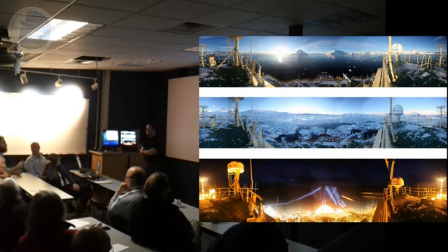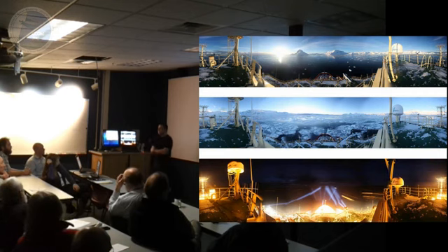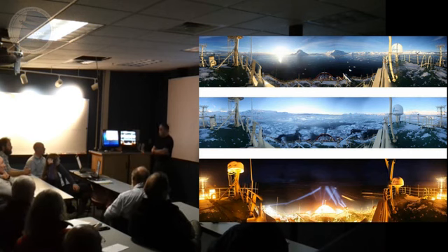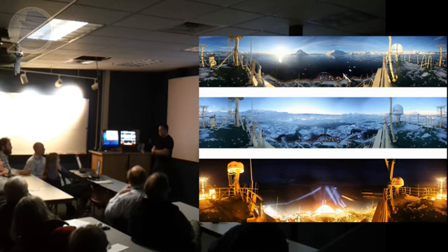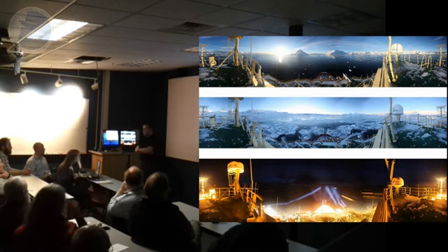Yeah. Monica, you had a question? Yeah, well, this might be moot now if you're not going to use a pan camera again, but if you wanted to, could you maybe solve your problem by using maybe rubberized shock pads? I mean, that might affect your positioning a bit, but your yaw and your roll and everything is going to be much lower frequency than all the shuddering when you're in the ice. So if you could shock pad that to maybe decrease that.